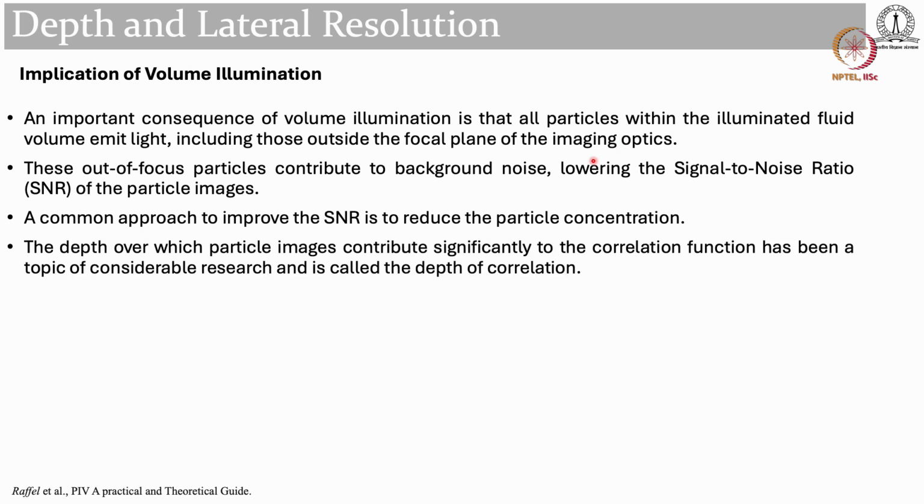Another concept which is really important, which I'll be briefly discussing here, is the depth over which particle images contribute significantly to the correlation function we are talking about. This depth is known as the depth of correlation, which has been a topic of considerable research. You can read a lot of papers on this topic. Here we are talking about the particles which significantly contribute to finding the correlation peak, right? So basically this is the most important thing, because this is what gives you the output which you want.